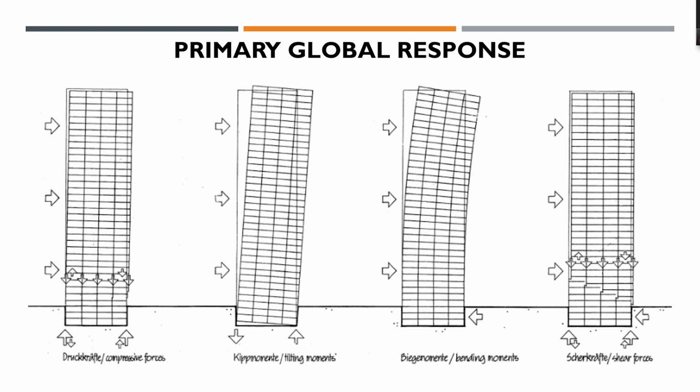And as engineers, we should find each one of them separately, because each one of them has a different meaning in the check, right? So drift is this kind, shear deformation between each floor. We are very concerned about drift. Overall deflection, we are concerned about because of the overturning and so on. So we have to check each one of them. These are the primary ways the building can deform due to lateral loads, and they are all independent phenomena combined together to get the total deflection of the building.